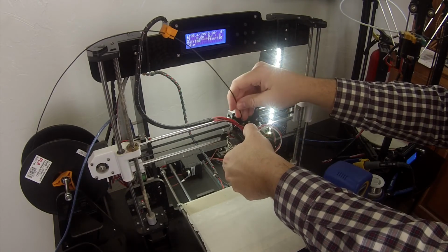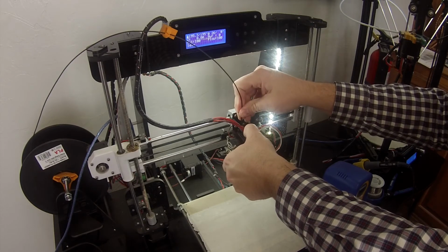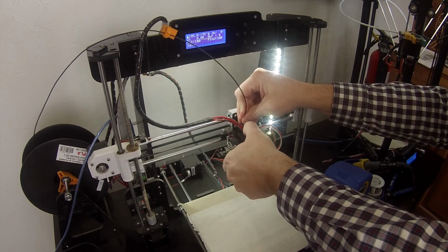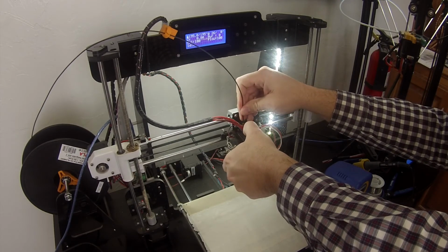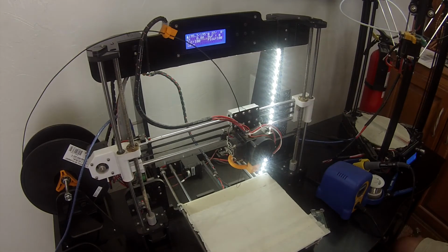Relieve the cog tension, feed it in, and find the proper pathway just by feel. And pushing some out by hand is no big deal. It gets it properly primed, and you're set. I usually let that dangling plastic cool for a second, grab it with my hand, and we're pretty much ready to go. So at this point, the machine has proper plastic fed into it.